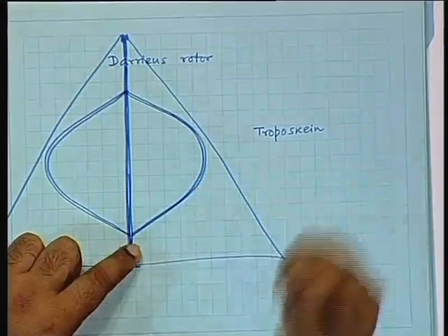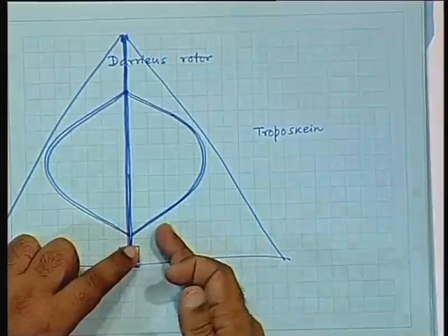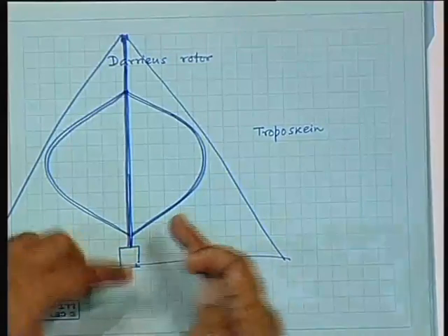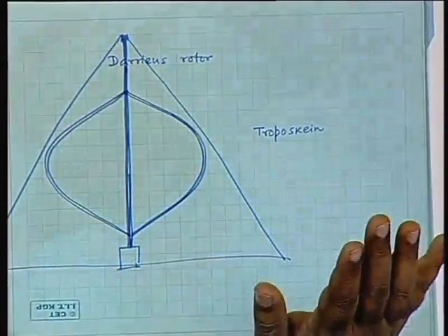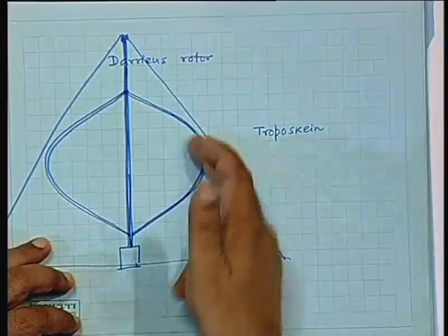Do you understand? There cannot be any bending stress, because if it were flexible and rotated, it would take the same shape. And if you make it in that shape, then the only force that can be produced is the tensile stress that stretches. That's all.